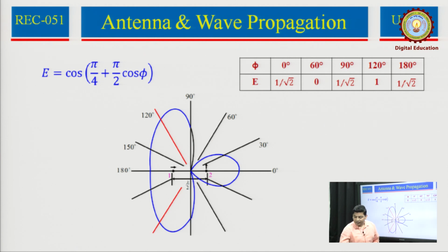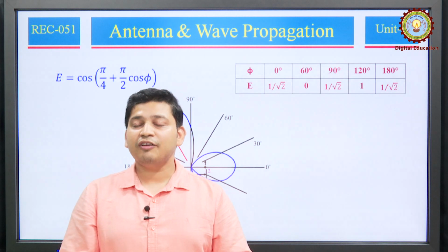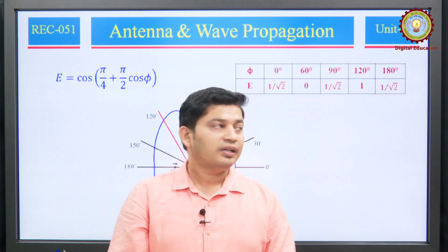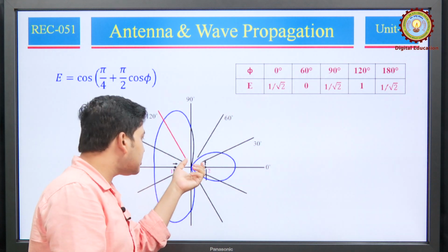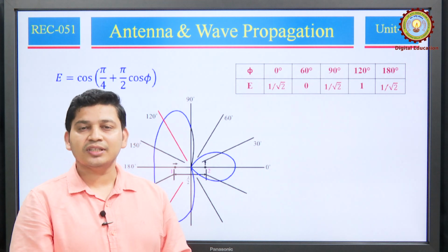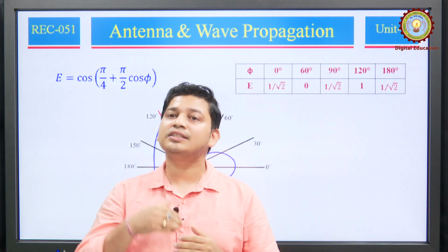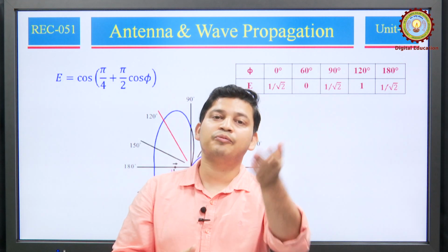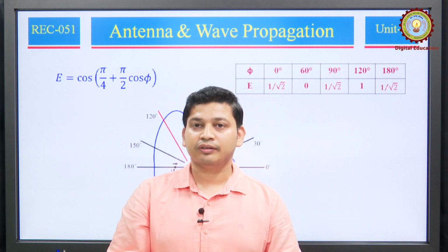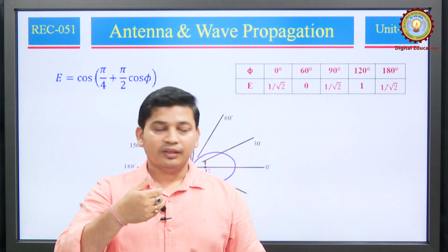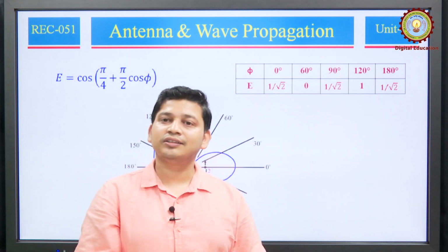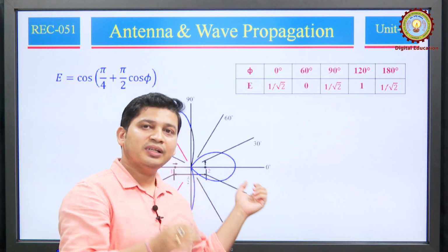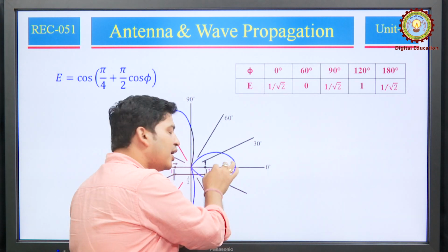So, from the conclusive point, if there is existence of phase differences, it may govern the existence or possibility of side lobe and back lobe there, because as an RF engineer we always want our main signal strength to be in the forward direction, toward the receiver side where we want to communicate or send the signal. But it is also shown from here, there is always existence of some minor and back lobe. We cannot minimize it to 0 value, but we can take the minimum value as possible.